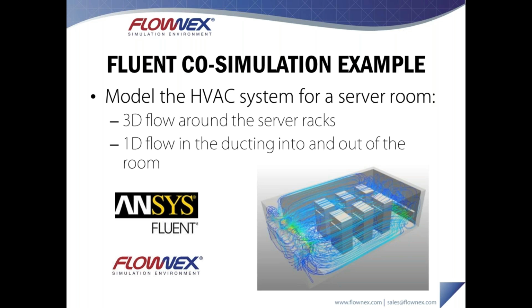What's also useful in this application is three-dimensional models often have boundary conditions specified in relatively arbitrary positions that are difficult to measure. So, for example, if you're trying to characterize the performance of your boiler and understand the heating inside of that and the temperature distribution, specifying boundaries at your boiler mouth, for example, might be a difficult place to receive measurements from your plant.